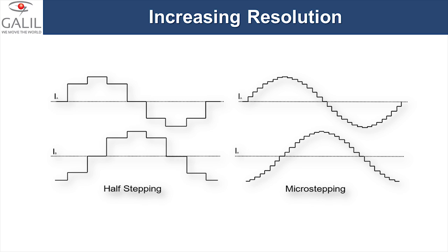the phases of the stepper motor partially. When this happens, the stepper phases fight one another, and the resulting position of the motor is the location where the two forces find equilibrium. In all cases, the number of steps is increased by further breaking that sine wave into more and more discrete microsteps. This gives the stepper motor the ability to have 2, 4, 8, 256 or more times the resolution it previously had. That takes the motor from 200 steps per revolution to tens of thousands of steps per revolution.